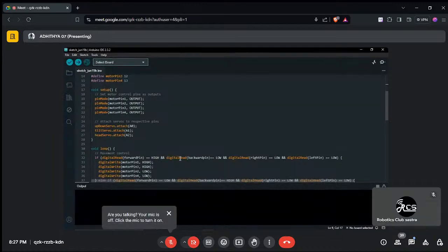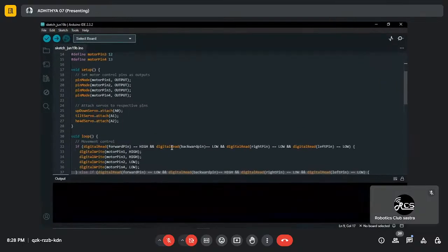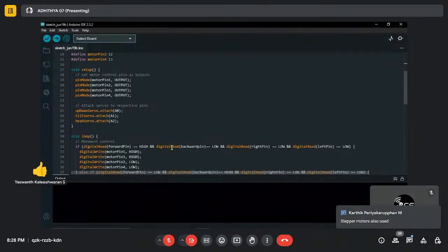You can also use DC motors depending upon the application. Servo motors are only for low torque purposes. In industrial manipulators, for demonstration purposes we are using servo motors, but for industrial and real-time applications they use DC motors, because there is a need for high torque motion for the manipulator. The base motor needs to bear the weight of the entire manipulator, the entire gripper, the motor connected between the gripper and the connecting rod. Sometimes they also use stepper motors, which are more efficient compared to servo motors.